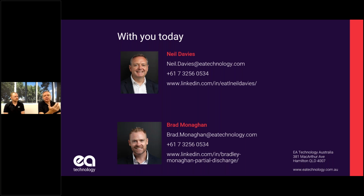If you're only going to do handheld, my personal recommendation is always very much a test soon after energization, and then at 6 months, and then 12 months, and then maybe go to a 12-month period. And that's for switchgear and cables, because that's a critical time, and infant mortality is a thing, as we've seen. And also, if it's switchgear or cable joints, you might actually be under warranty for 12 months. So it's always worth finding the problems first.